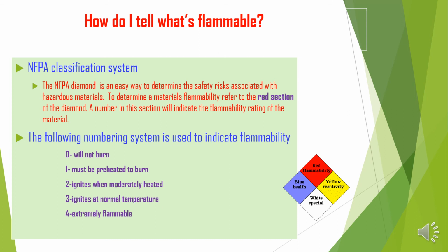It can burn. 2, it can ignite when moderately heated. If there is moderate heat, it can ignite and cause fire. 3, it can ignite at a normal temperature, without any heat, and cause a fire. 4, it's extremely flammable. It can cause a fire under any circumstances. So you will deal with it according to the number mentioned in the red division.